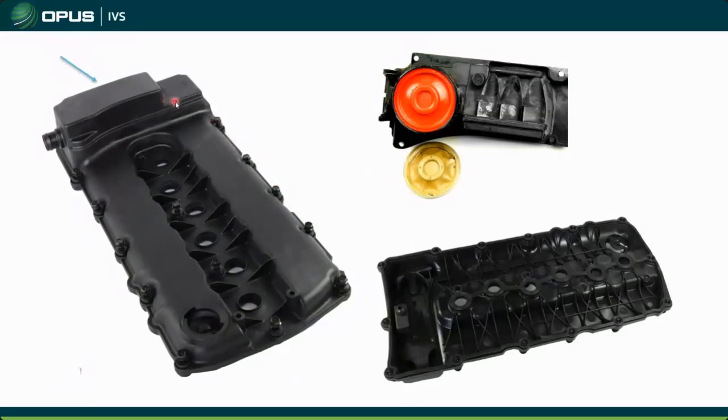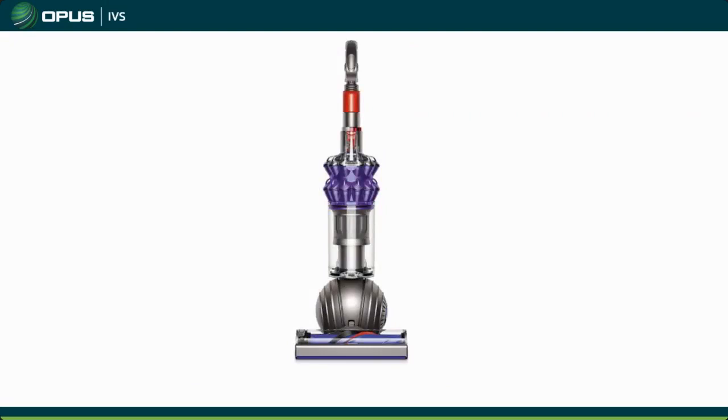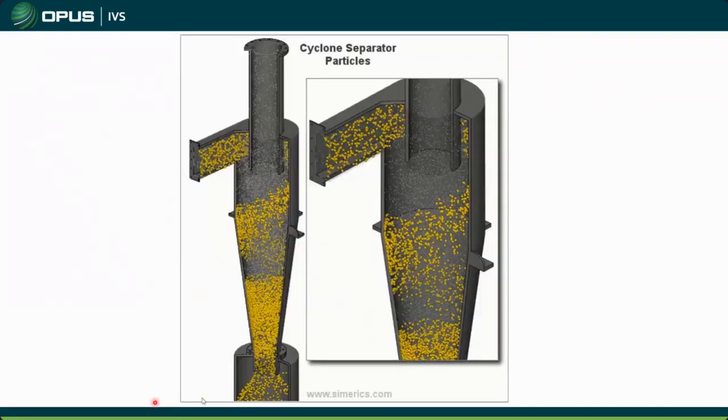Now, also in here, you have some oil air separation. This is a good instance of where they use a cyclonic separation system. These little cones here are actually part of this cyclone system. Now, where do we know this from in daily life? Dyson vacuums. They love to talk about this cyclonic action. Well, we use that same physics principle for oil air separation in a lot of our vehicles. Here we have an example of that.